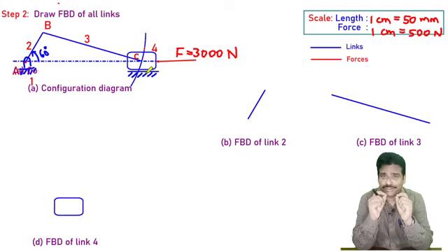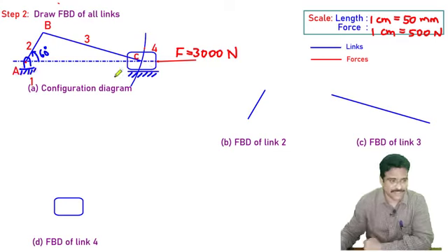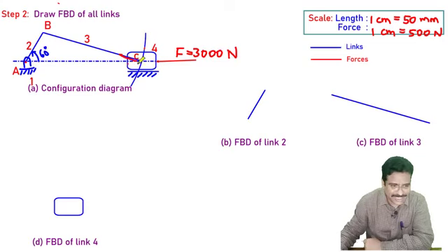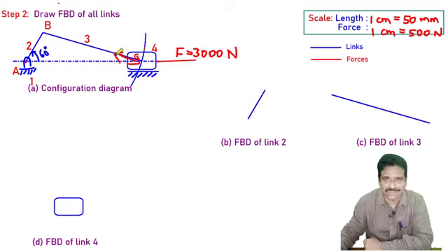Now we will be showing various forces acting on those links, for which we must be aware of the applied and constrained forces concepts. If you take link 2, what are the forces acting there? Of course, there will be some force from 1 to 2. In link 3, the force will be acting in the opposite direction, along the link. This is what we call constrained forces. Constrained forces always act in pairs. Similarly, here I will have one pair of constrained forces.